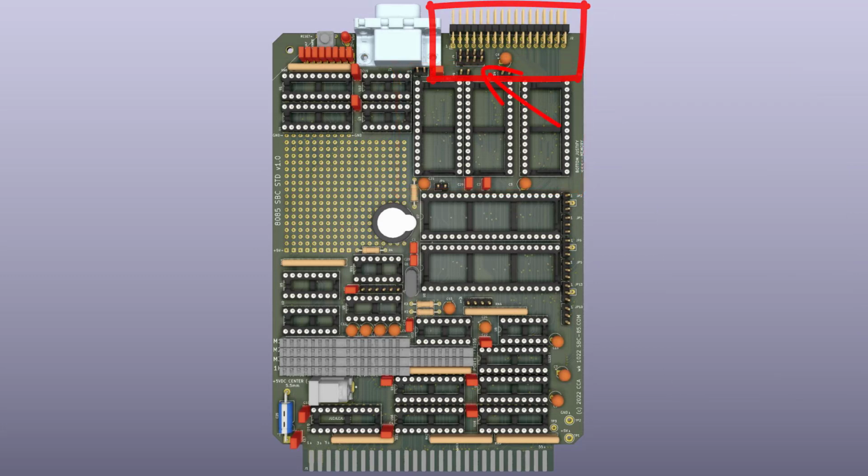This is the header for the 8155 I/O, as well as those 8 extra. This is the little header that allows you to pick up different signals from pins around the board and wire wrap them up to this off-board connector. Then towards the left, we've got the serial port. We have the reset switch, and there's LEDs here to show us that we have power and which memory map is in use, and then the other 6 LEDs that you can just play with on the outboard port.